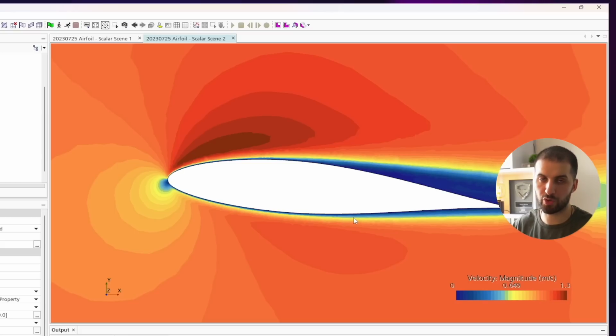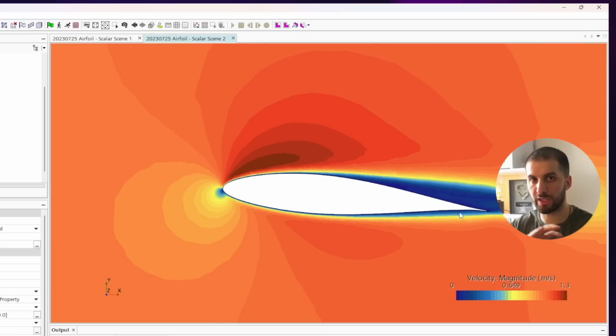Of course, if you want to compare to experimental data, what you could do, for example, is plot the points of the experiments, and there are some tools where you can kind of go to a paper and define the x and y axis, pick all the points, and it saves you in either a MAT format or a CSV file. Then you can overlay the simulation results of maybe a line that you have defined across your profile and kind of have virtual probes inside of your simulation, virtual sensors, where you can validate your simulations with experimental results if available, obviously.